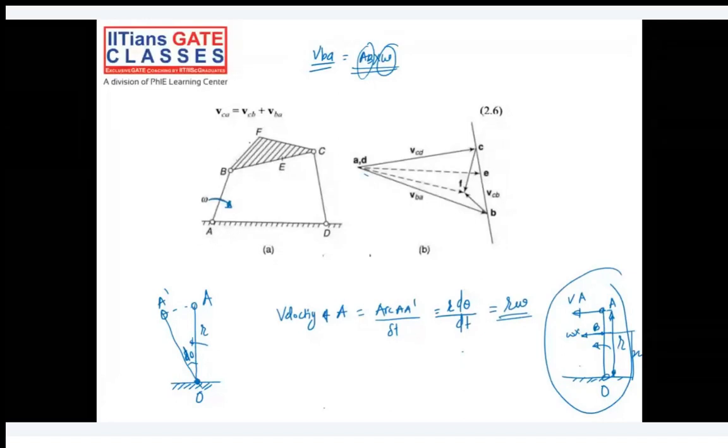Sir, E was understood, because you have given the logic of R and X, that corner point. But F I'm also trying to explain here. See, how you are calculating F, it is not any separate link. F is part of the BC link itself. Are you following? It is like a link which is having three ends, B, C, and F, but we have not connected it to anything. Entirely it's a rigid body.